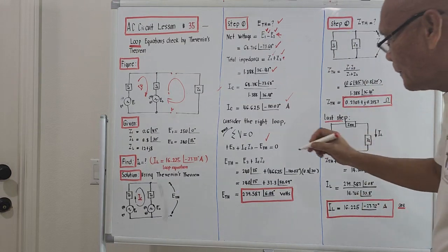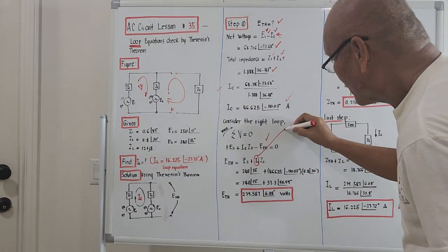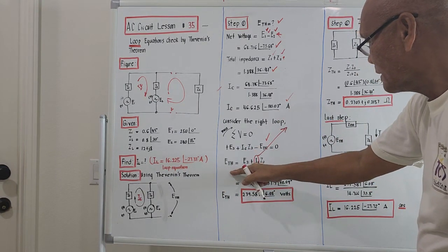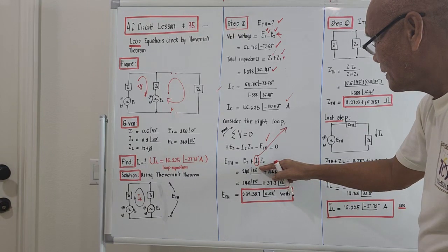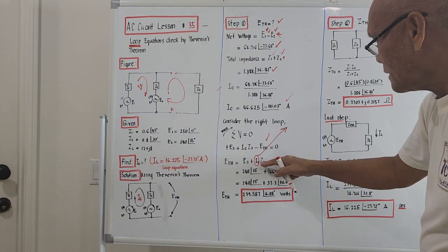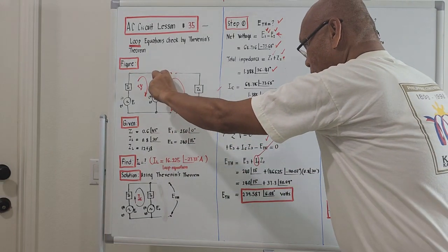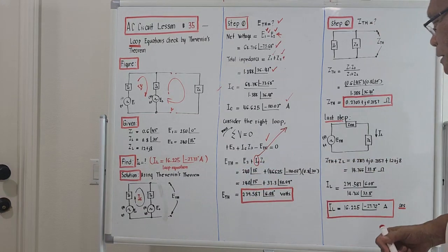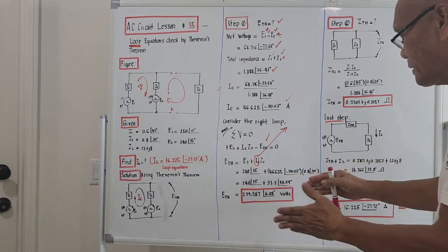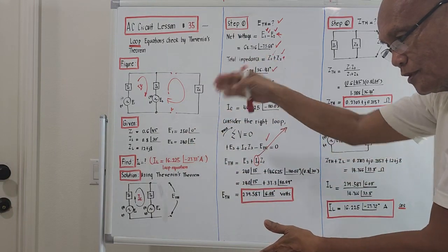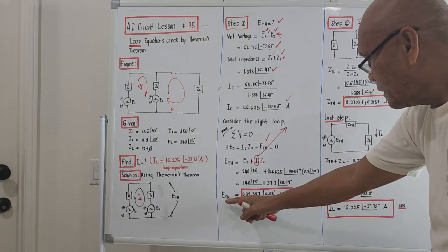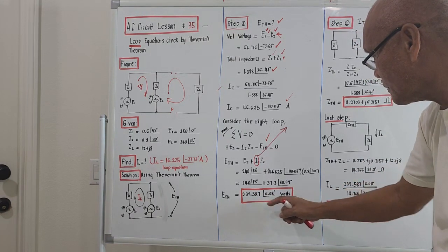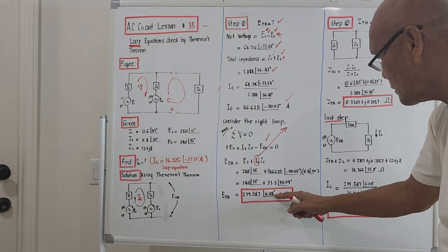That's why we computed I sub C a while ago. That's the importance, because in the computation of the open circuit Thevenin's voltage, we need I sub C. If we multiply IC times C2, it will be the voltage drop across this. Performing this operation, I will not go into detail already, as some parts were shown in the previous example. What will come out for ETH, meaning the Thevenin's open circuit voltage, is 239.587 angle 66.08 degree volts.